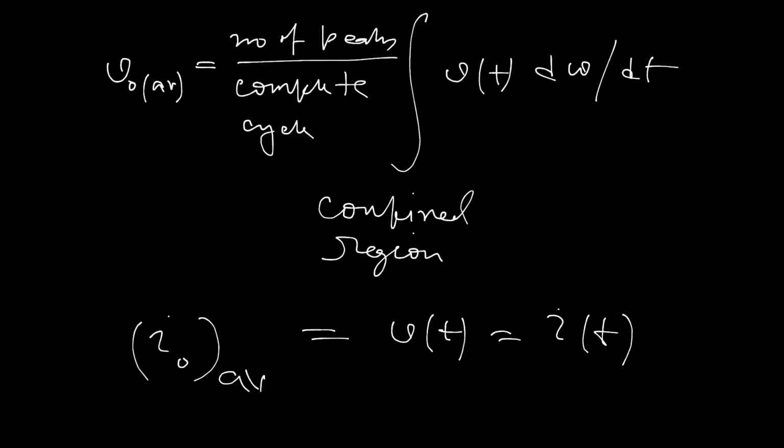So in this way we can calculate all the parameters for this kind of electrical circuit, in case of any kind of rectifier circuit. Okay, so we can be sure that the average output voltage should be based on the number of peaks in any direction. Normally you can consider the positive half cycles. How many peaks are there in the positive side, that is the number of peaks.